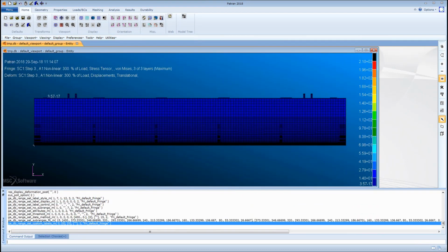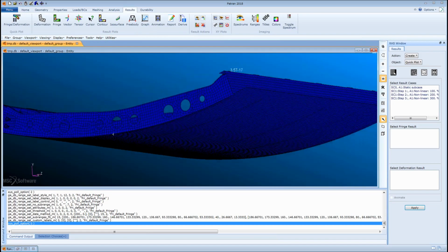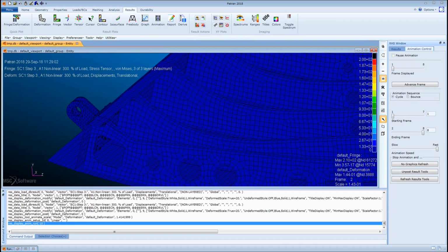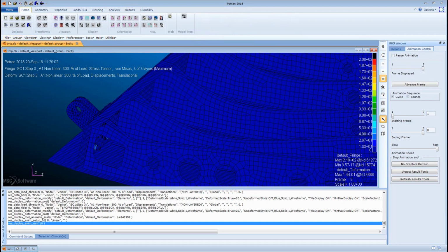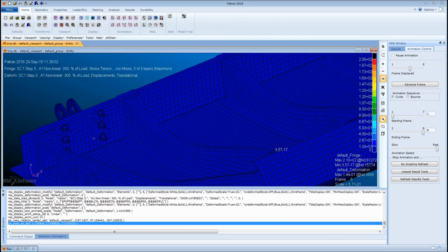We've automated this particular example to work with a third-party toolset, so we're reading the exported MSC Nastran output into the post-processing environment, again in an automated fashion, and we're looking at the MSC Nastran HDF results output specifically for contact status output from this nonlinear run.